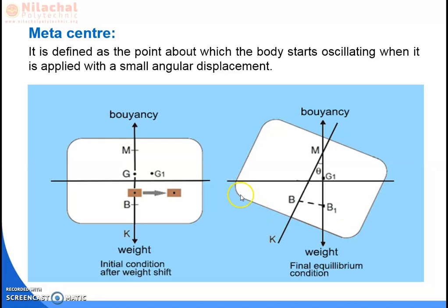We have seen that this is the portion of the body, and this portion of the body changes its shape. The body is tilting rightward, so the amount of water displaced at the right position will be more. In the earlier case, the weight is acting along the vertical direction, but here, due to the rightward motion of the body, the weight of body is at an angle of theta, and this makes a turning effect, or moment, applied by the weight of body towards the right.